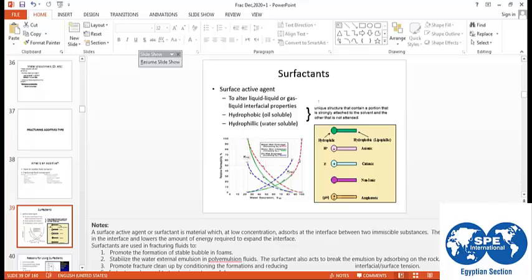You decide the concentration of breaker according to the result of this test. With different concentrations of the breaker, you will have different breaking times. You will select the correct concentration according to the breaking time required.